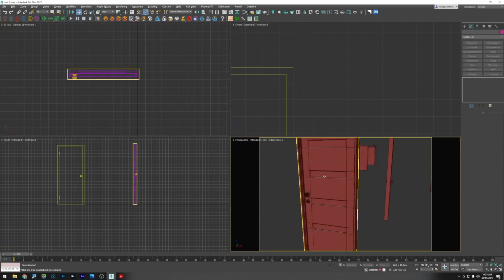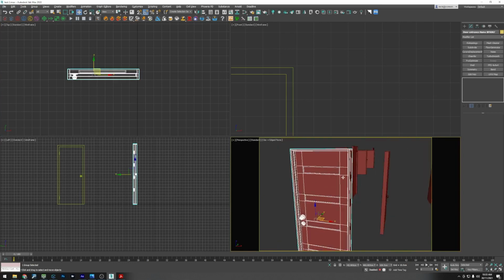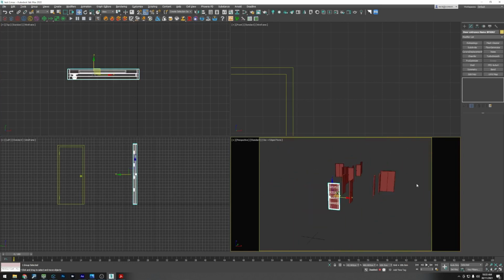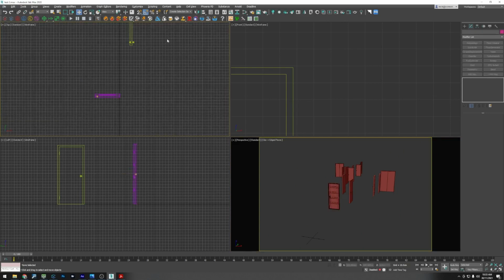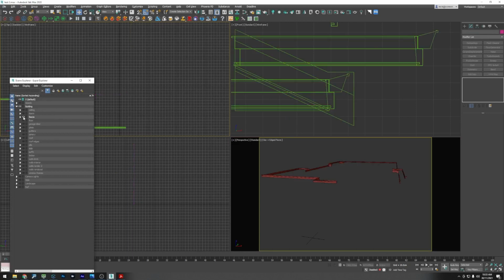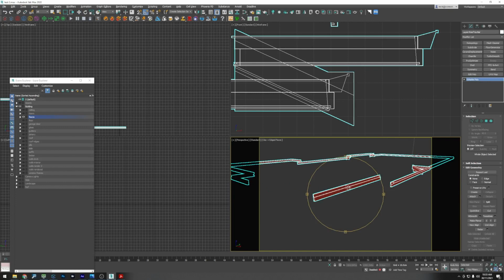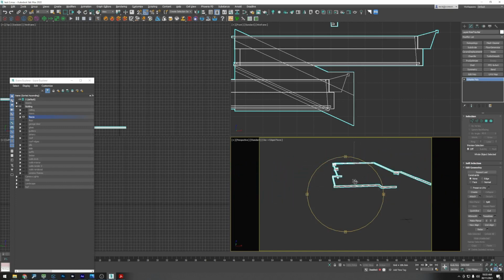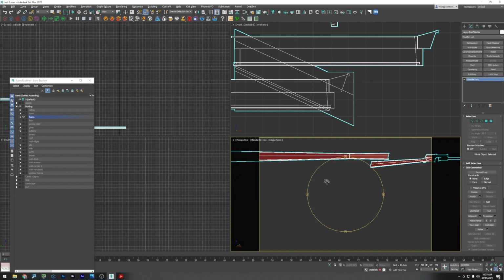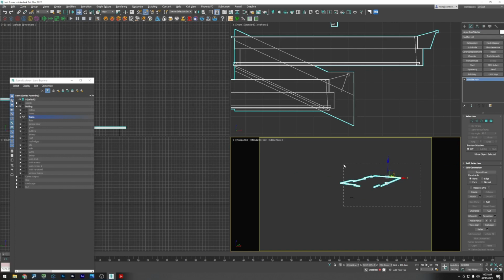Okay, so now we can see the door is just much more detailed and photorealistic, so that'll render a lot better. All these other doors are inside the house, we won't see them, so we can leave them alone. Go back into our layers, so the doors are good. Fascia, as I said, a lot of the time these fascias and gutters are a specific profile, so there is a process for remodeling them, which we've got in another tutorial. So for now, that's fine. We're just going to add a UVW box map to them all.